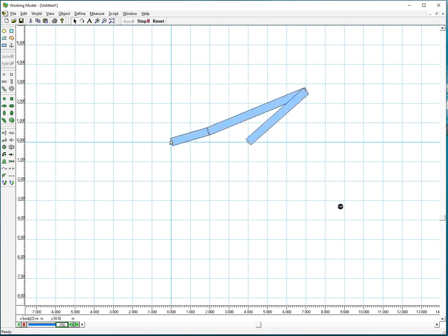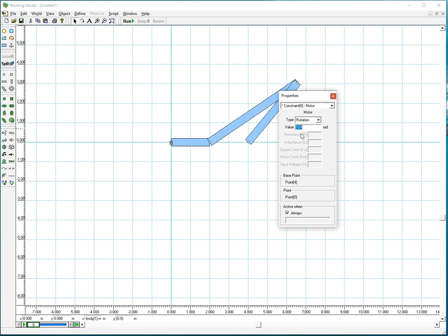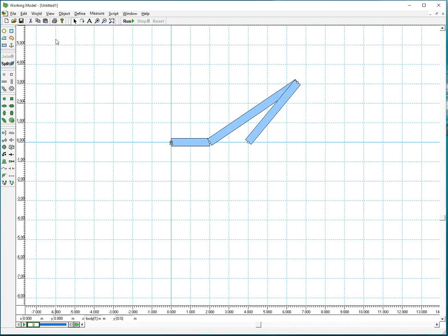All right, so the type of input again was rotation, and it's the way I define. I used formula language. So 10, if I have radians, then this will be radians per second times time, t, so it's equivalent to the crank rotating 10 radians per second.